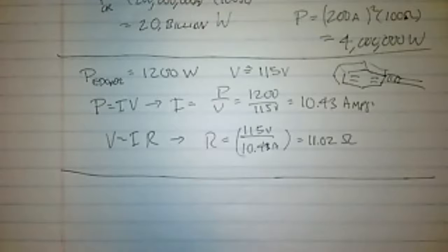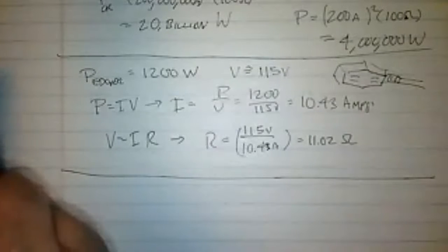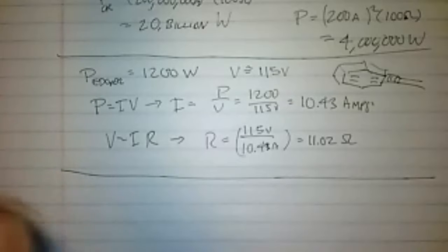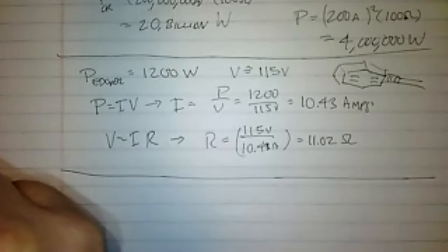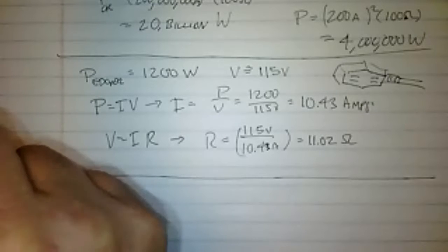Where the AC stuff comes in is the alternator. It takes a belt off the crankshaft, or one of the shafts that's spinning, and runs it to the alternator. The alternator spins at that rate and turns little magnets inside a bunch of coils of wire. Your book has a picture of an alternator, by the way. I think it's not in this chapter though.